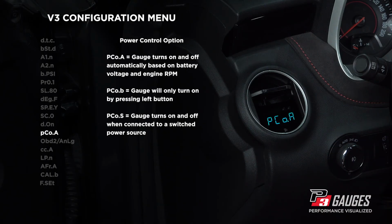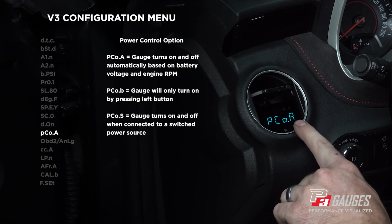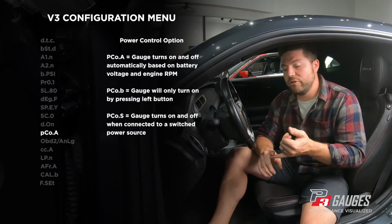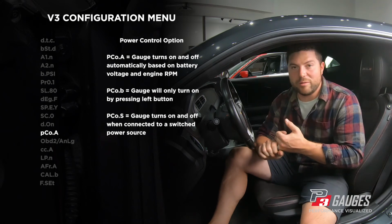This is your power control option. That's what the PCO stands for. So we've got PCO.A, power control option, automatic. This is the default setting. Right now, the gauge is looking for battery voltage and RPM input to know when to turn on and off. It will not turn on with the ignition. It will not turn on once it's plugged into power.